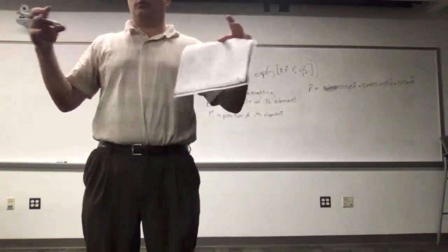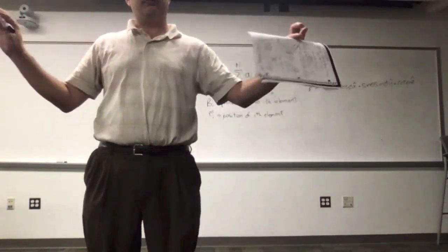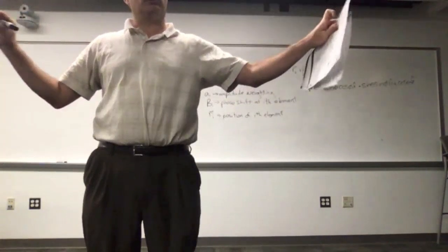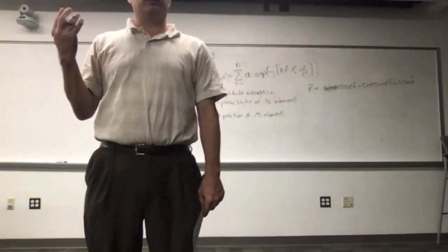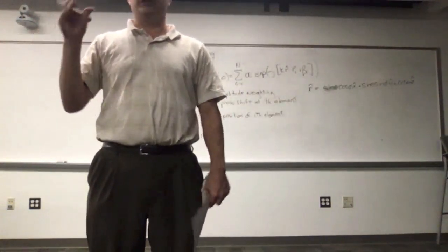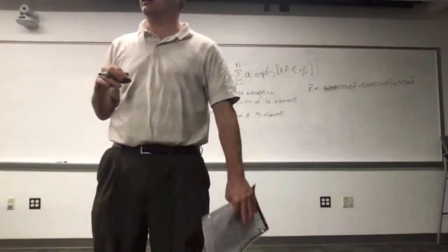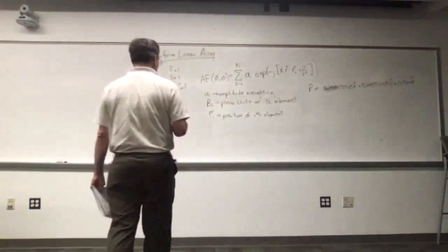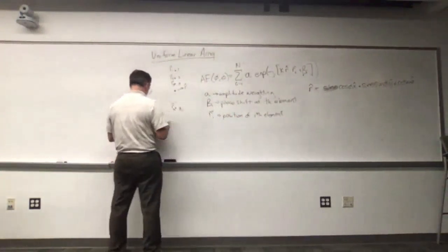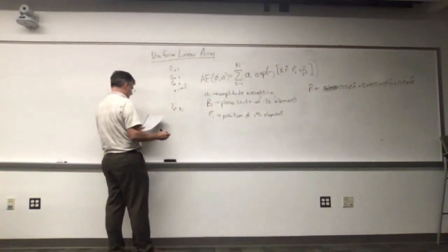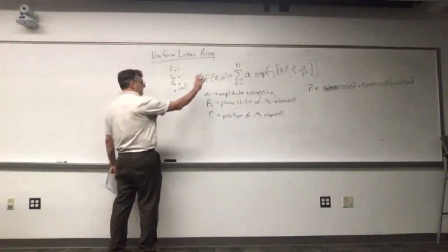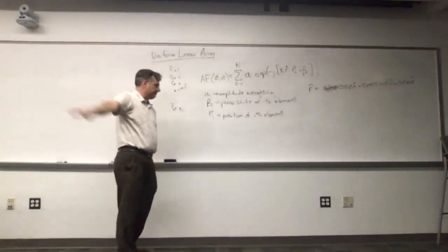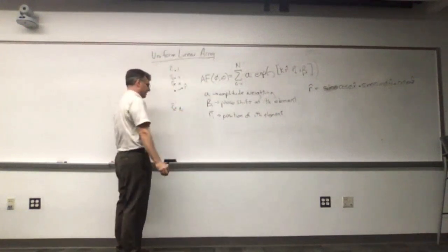Make a nice uniform linear array, and then at the end you start tapering. You're making smaller and smaller amplitudes, not just playing with the phase. It gives you an extra degree of freedom to kind of smash down those side lobes. You never get them to 0, but you can get them really far down on your array properly. So the linear array is really this general case. This is the expression you can use in the array factor of any arbitrary geometry.